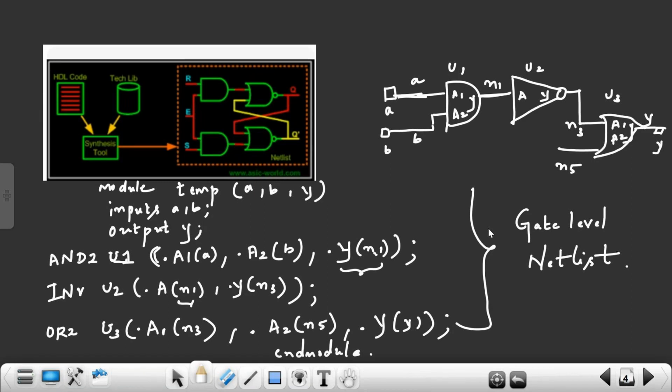Does the instance count change from synthesis to PNR? We give the same netlist, but it can change for sure, because in PNR we will add different cells again. We add some cells in the PNR stage to meet timing violations, but functionality should not be affected. So the instance count, which means cell count, will change in PNR, that is, in placement and route.